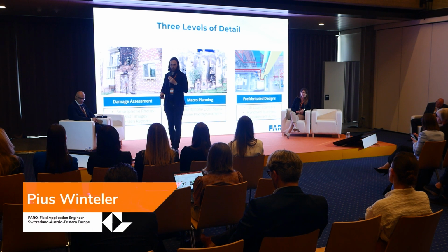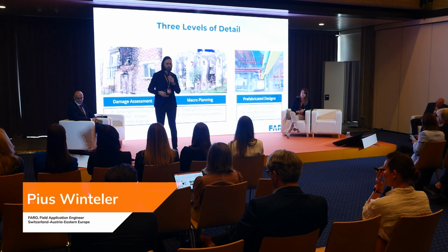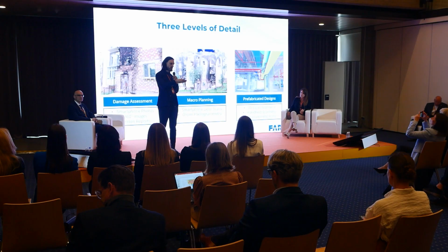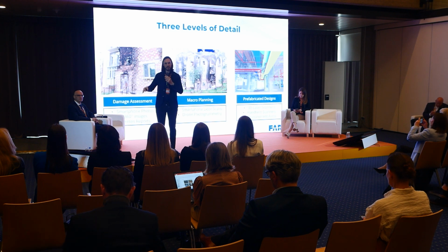When we want to go into macro planning, where we then generate plans out of it, BIM models, we then utilize also smartphone and LiDAR scannings or drones to get an overview of what's going on. But the highest level, I would say, is then prefabrication designs. So when you want to go into prefabricated design and not finalize your fabrication on the construction site, but finalize it in different fabrication buildings all over Europe, you just need to have a millimeter accurate documentation of what is going on there. So because you can make this documentation remotely, you can make this documentation on site in Ukraine,